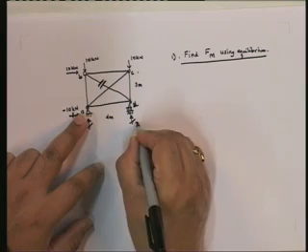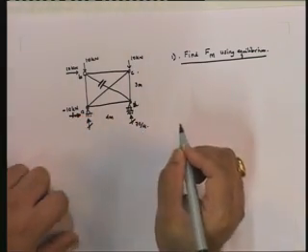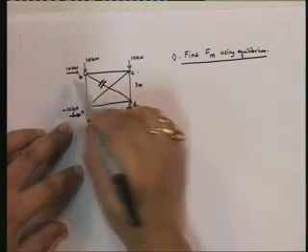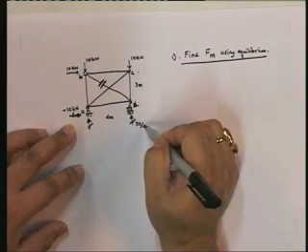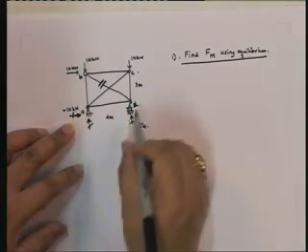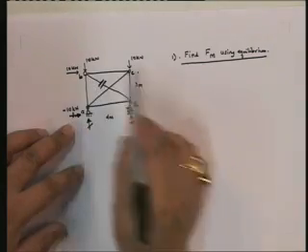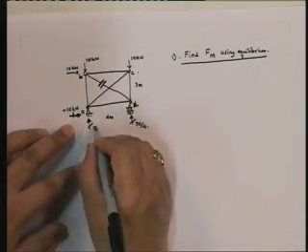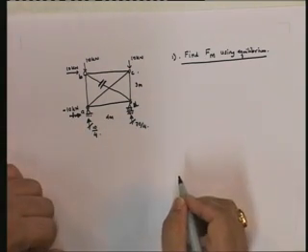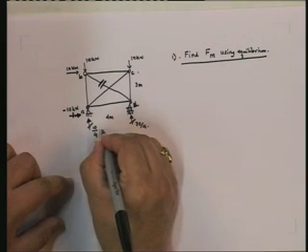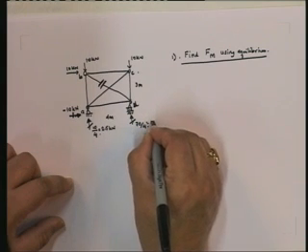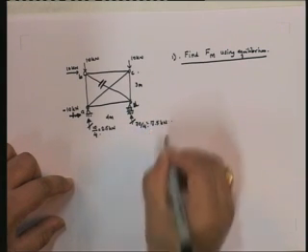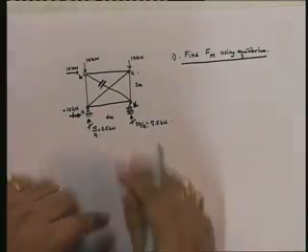So this is going to be equal to 70 by 4, because 10 into 3 plus 10 into 4 is going to be equal to 70. 70 divided by 4 is 70 by 4. And since this plus this is equal to 20, this is going to be equal to 10 by 4, which is equal to 2.5 kilonewtons, and this is equal to 17.5 kilonewtons. Okay, so we've got the reactions for the support.